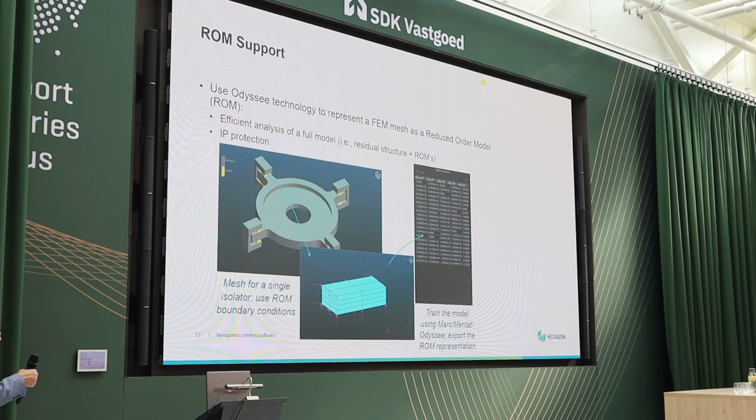You, as the creator of the reduced order model, should know the dimensions and the typical application range, so how large the displacements of the interface nodes can be. You can set up the DOE space, and that's done using a library from ODC embedded within Mentat. So you don't need to go to the ODC software itself, but you can immediately generate this DOE space in Mentat and then use it in your training runs using Marc. Mentat will automatically create the necessary data for Marc.